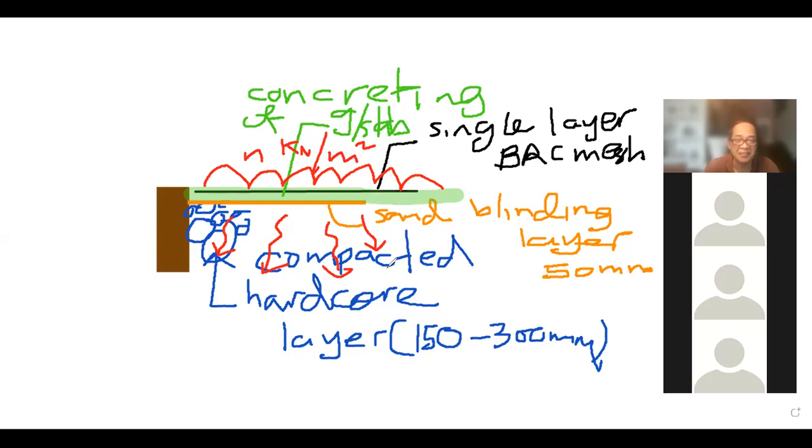Okay, so this is a typical non-suspended ground slab construction, and usually this sort of construction is adopted for good bearing capacity soil, that is, with a high bearing capacity, or typically for cut areas. Previously in your IDP 1, you have your cut and fill area. Certain parts of the development are cut area, certain parts are fill area.